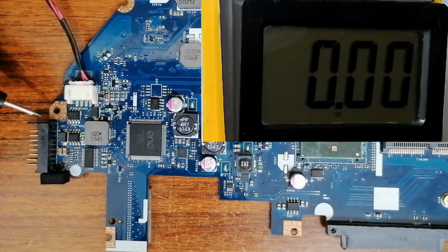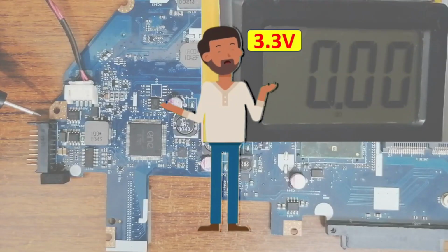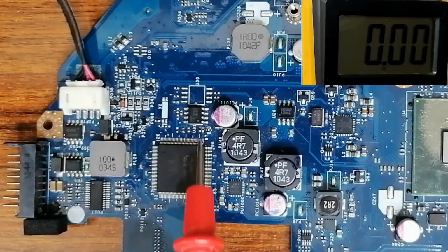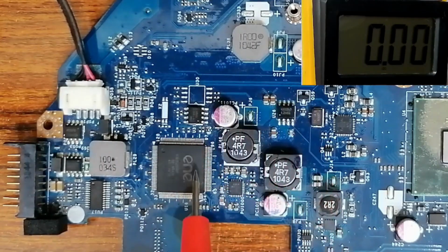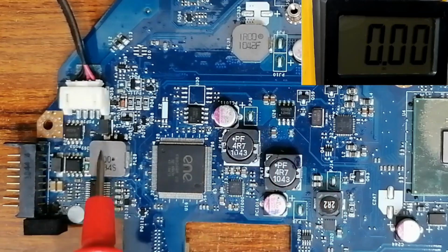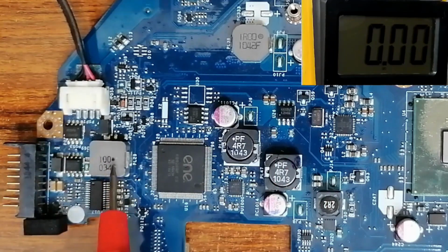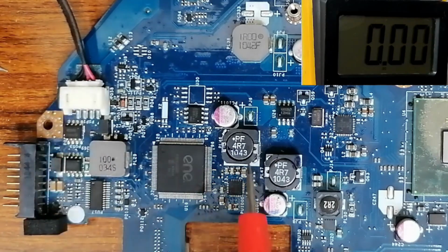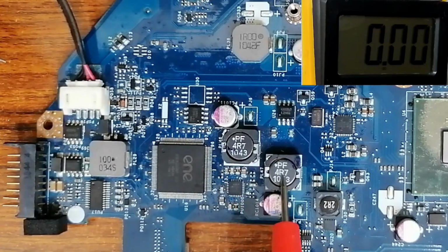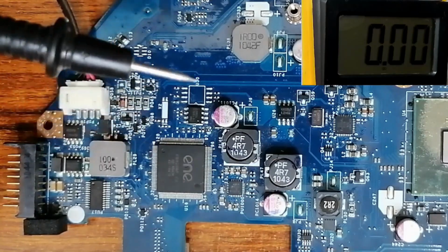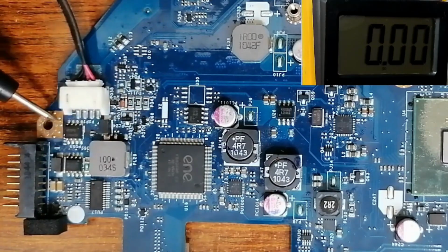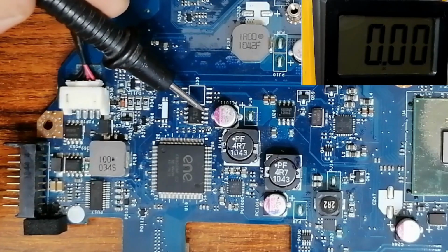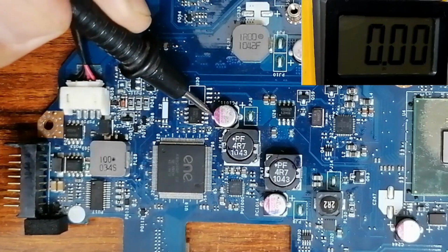The second voltages that we gonna check is 3.3 volt and 5 volt. Here we have 3 volt, 5 volt circuit. You're going to find it usually near to the charge circuit. And of course, the charge circuit is always near to the battery connector and DC connector. So here we should find 5 volt in one inductor and 3.3 volt in the other inductor. So let's put the black probe in the ground here. Let's check, for example, this time the negative terminal of the electrolytic capacitor.